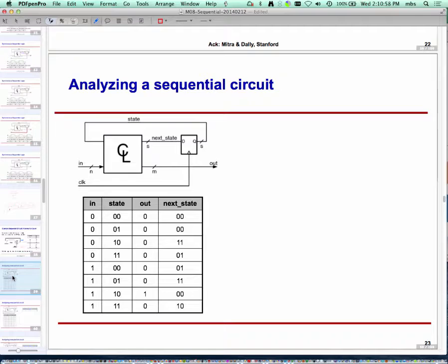Now, when it comes to sequential circuits, there are several different types of problems that you would encounter. One is, I'll give you a complicated description, like we have seen in the homeworks, the thermostat example, the midterm. In those cases, the system was doing a pure function. In other cases, I might ask you to design a system where the system needs to remember something about the past. So those are problems of design. Then you also have problems which go in the reverse direction. Given something, you have to figure out what it is doing. So you might be given a circuit where there is some combinational logic, some flip-flops, and you have to figure out what it is that it is doing. That's the analysis kind of thing.